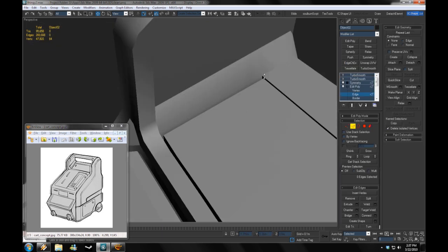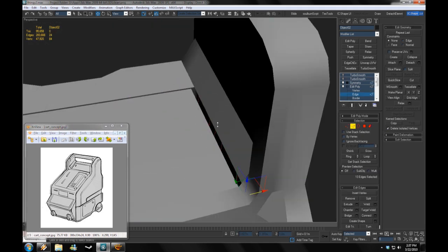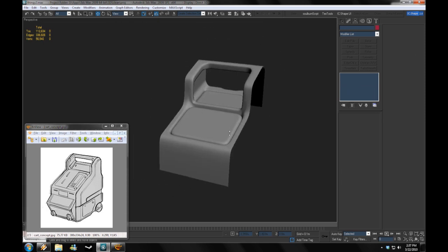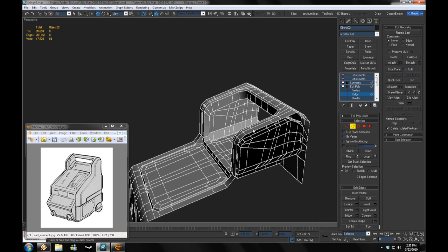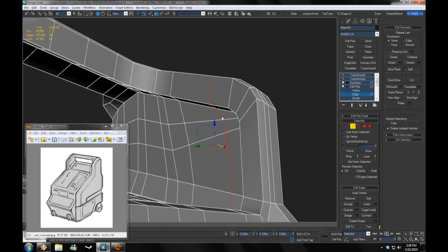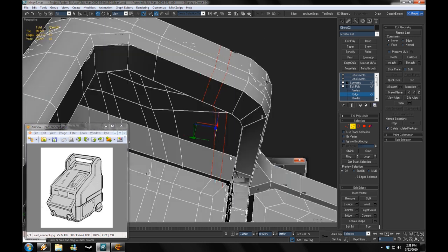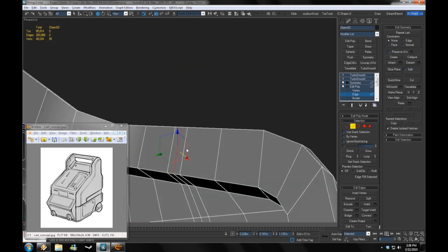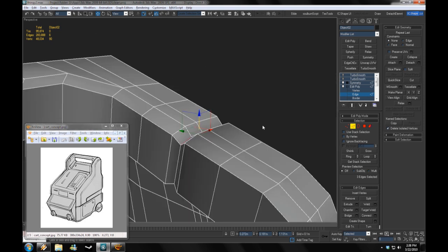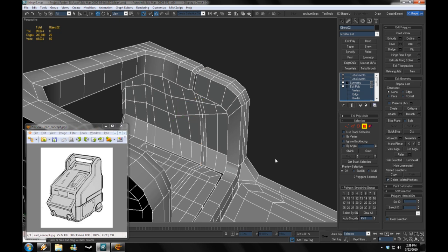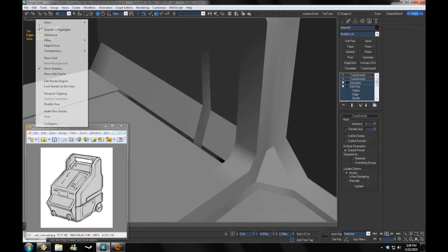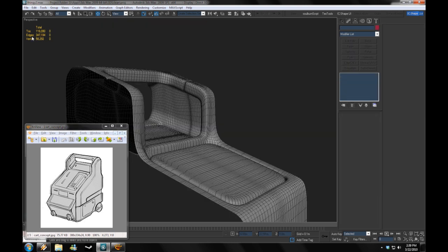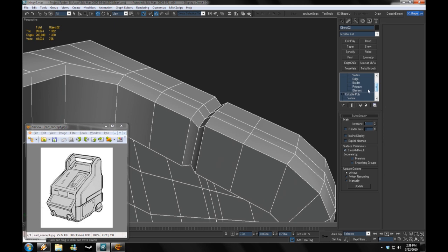It'll just help you make stuff faster, I suppose, is the best way. And you can kind of see me here defining some smooth groups, or in Maya you call them hard and soft edges. But anyway, you can see me defining the smoothing groups and where I want to keep the shapes hard, or where I want to keep the roundness going. It's not like a tessellate, like just using a straight tessellate modifier to make the mesh really dense, but instead it keeps your mesh flow so that you can get round shapes as well as hard shapes. Where with tessellate you would just ignore the mesh flow and add in edges wherever.